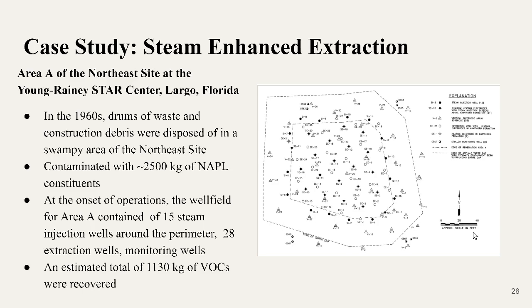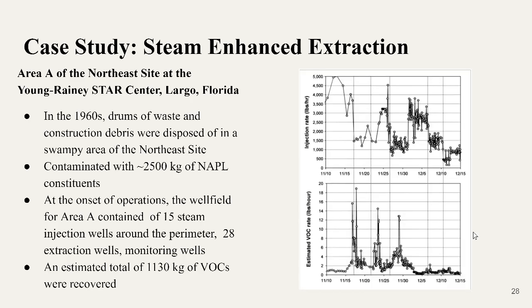Operations lasted 4.5 months and followed a strategy where contaminant spreading was minimized and recovery was maximized. Vaporization rates were increased drastically by conducting pressure cycling from mid-November until cessation of heating in February. In each cycle, the site was heated until steam flow from the extraction wells was steady, at which time a depressurization cycle was initiated. Slowing the steam injection rate reduced the pressure in the formation, leading to boiling of some of the pore water and chemicals present in the treatment volume.